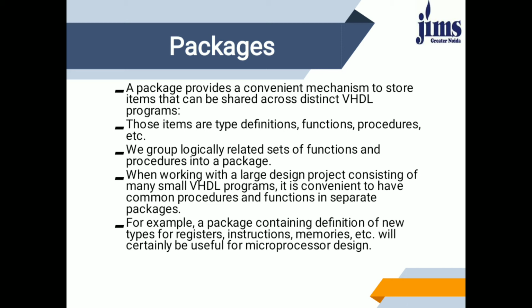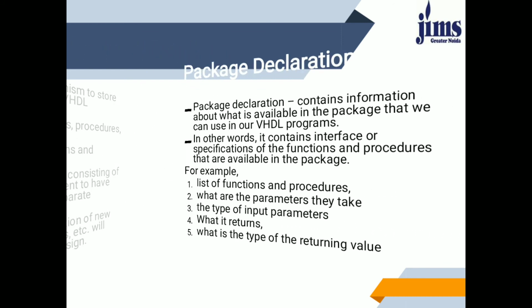When working with large design projects consisting of very small VHDL programs, it is convenient to have common procedures and functions in separate packages. For example, a package containing definitions of new types for registers, instructions, memory, etc. will certainly be useful for microprocessor design.